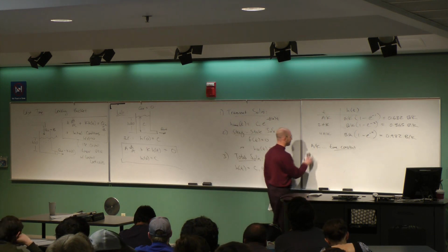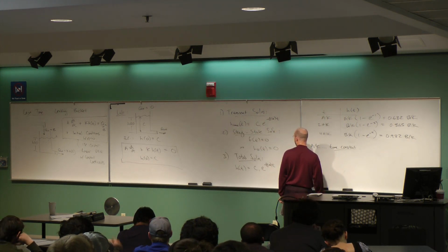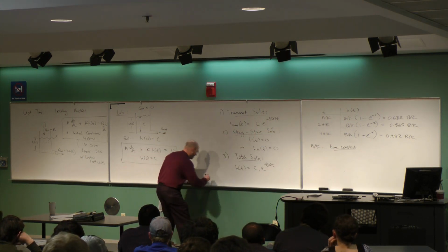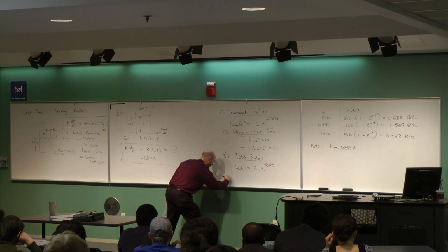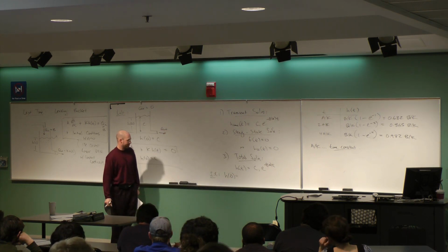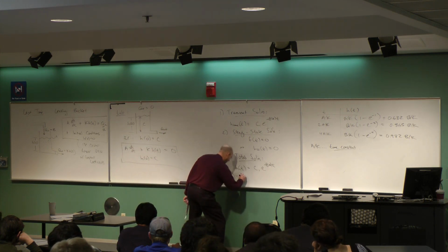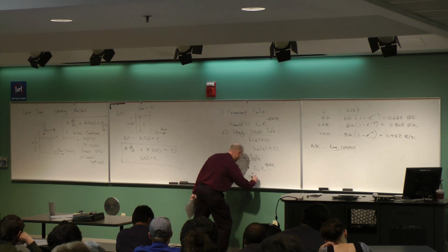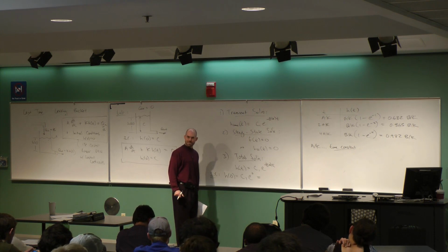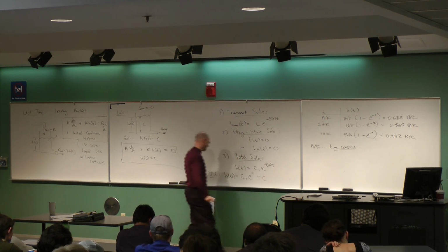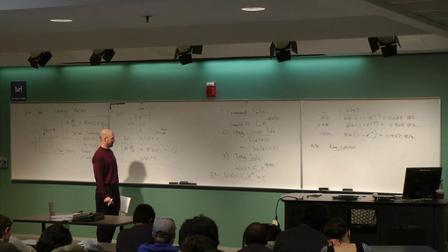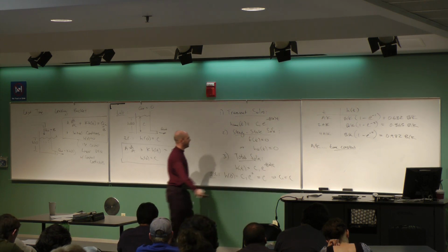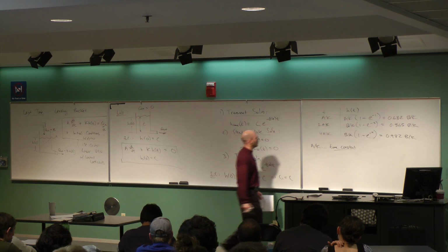And so what does that mean? Yeah, I need the initial condition, right? Initial condition, h of 0. What happens when I plug in a 0? C1 times e to the 0. And that is supposed to be equal to the initial height of the tank, right? Initial height of the water, which is C. So what's C1? That means C1 is C. C1 equals C. So, the lab problem, pretty simple problem, right?